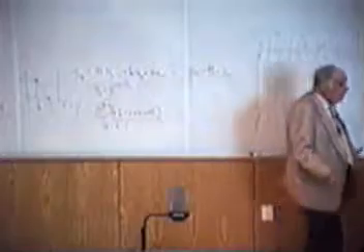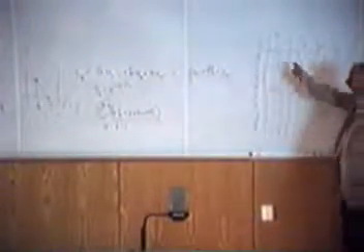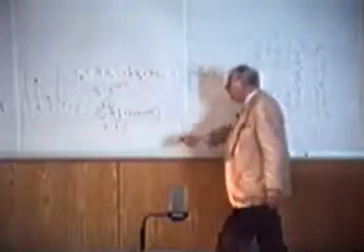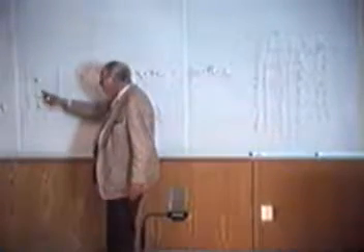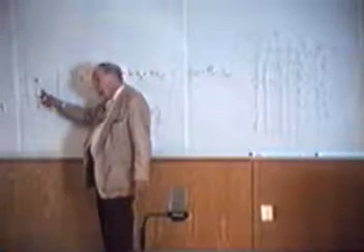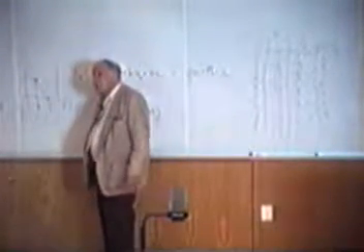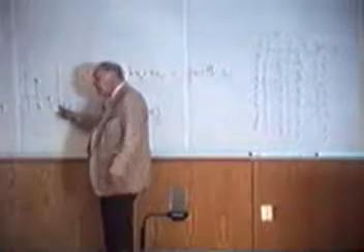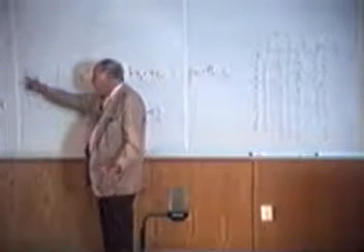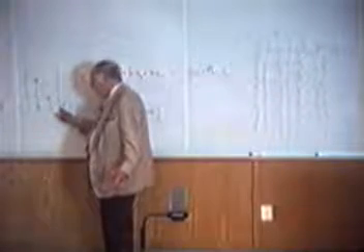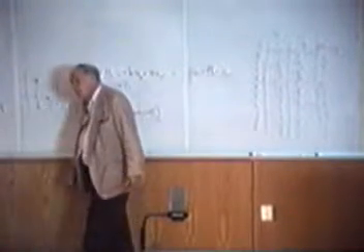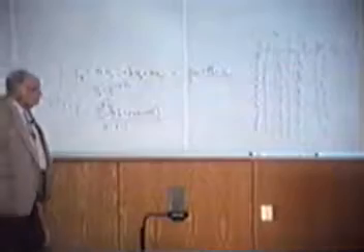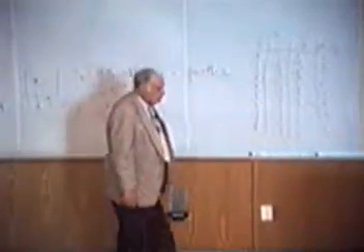Now, if you want to take other ones, for example, you want to take the half frequency between the two of them, you will find when you put it in, it'll come up with a value 1/2. Whatever value you had, the output value will be 1/2 as big. If you want to take this one, it's minus 1/3, I think. This is 3/2. If you put in all 1 0 frequency, you get out 3/2 as much, as you can see. So there is a very elementary digital filter in action.